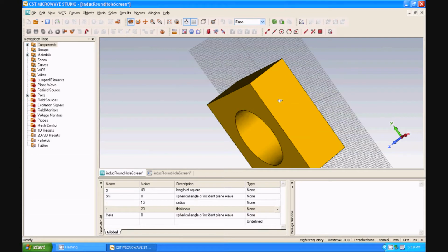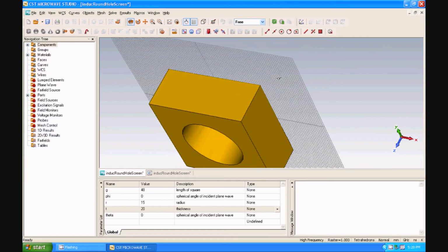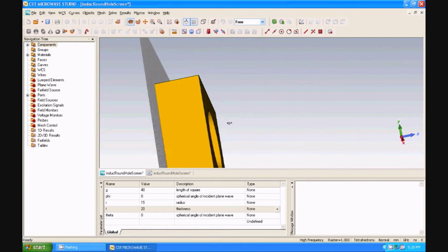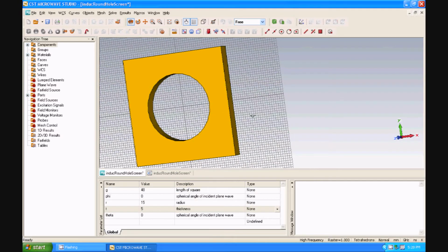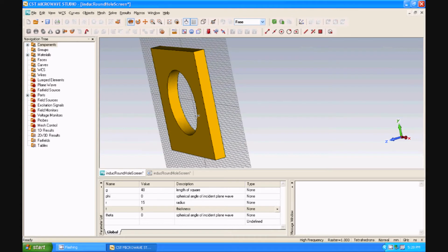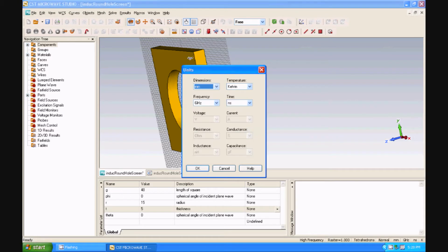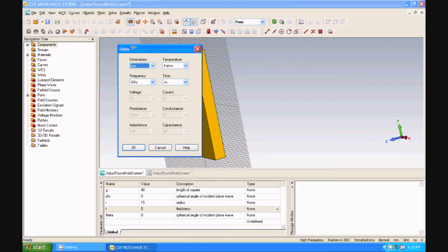Okay, so now that that's been covered, let's move on to step 2, which is setting up the simulation. The first step is to go and change the units. Now, in my research, we're primarily concerned with the terahertz region, which is infrared light, essentially. And we're also looking at visible light, but let's go with the terahertz region. So change the frequency to terahertz. Because it's terahertz, if you convert that frequency into wavelength, it will be on the order of microns.